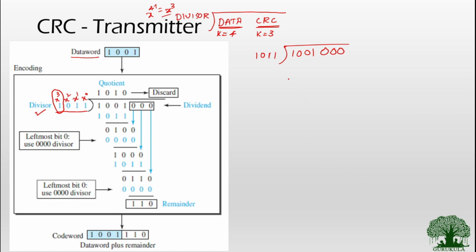Fine. So now I have the number to divide, and I have the number I have to use to divide it. Now it is good to go and perform the long division method. But there are two main differences. Wherever you perform a multiplication operation in the long division method, here in CRC you will have to perform a logical AND operation.